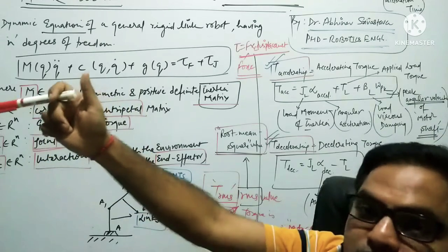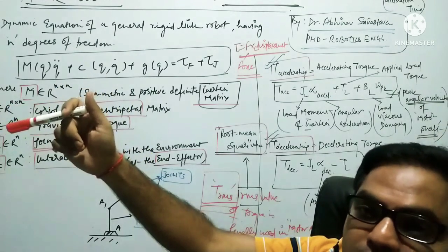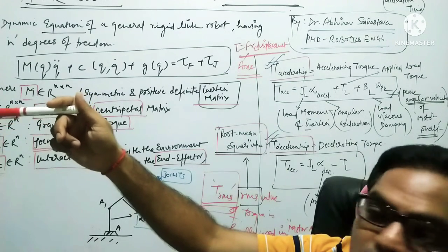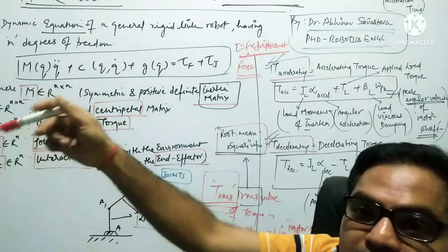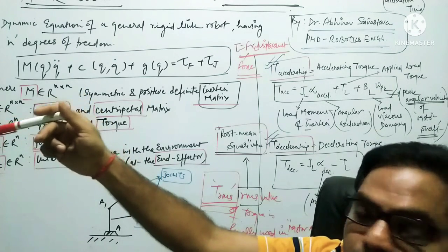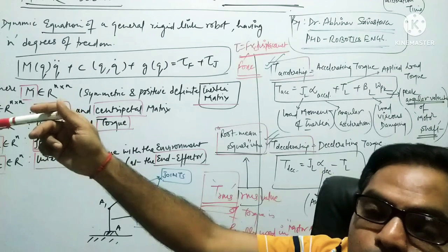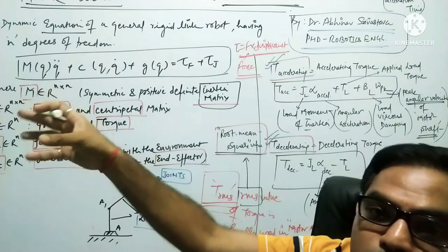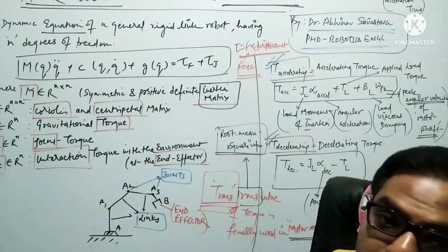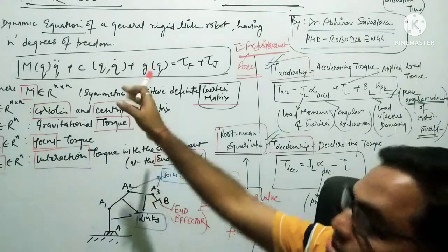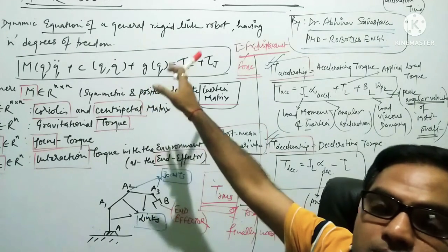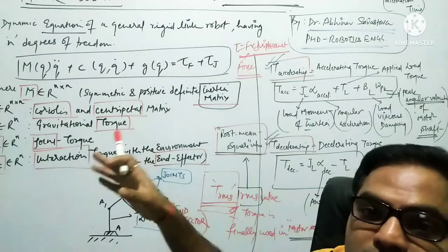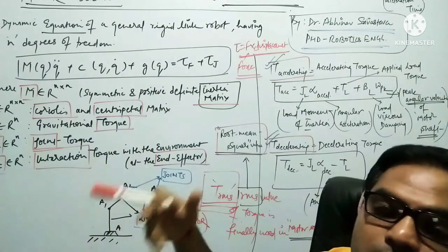The robot arm is fixed for a certain time instant, and at that instant the end effector is working, because if the links and joints are in an unstable position, then how will the end effector generate a proper force to grasp an object? That's why dwell time calculations are also there. I have not written it down here because of space constraints on the board. We have more important things to discuss than these subsidiary issues.